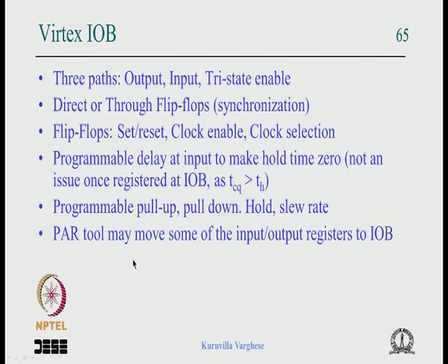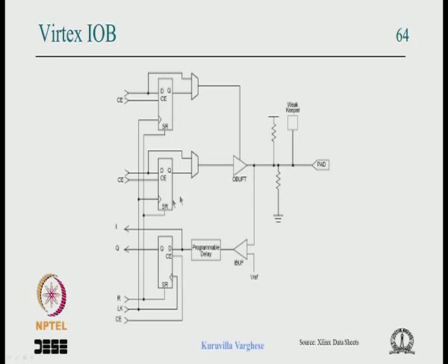Sometimes you have implemented something in a CLB, and that CLB output is taken to a pin or a pad. So what the tool does is that it will move that flip flop to the IO block, because it is very nice to have the last latching or registering at this point. If it is somewhere inside a CLB, then again you have to take the wires, that will add a lot of wire delay, and which may create timing problems with the following logic.